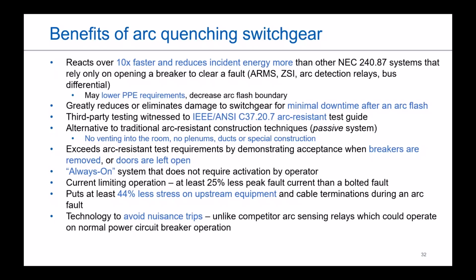We talk about an always on system. Unlike the maintenance mode, which is an administrative control, this is something that can always be on, not just when someone's near or in front of the gear. Because of that, whenever you experience an issue, you end up having less stress overall on your system, because you're not going down the same route of having to do a bolted fault where you're pulling in the maximum amount of current.